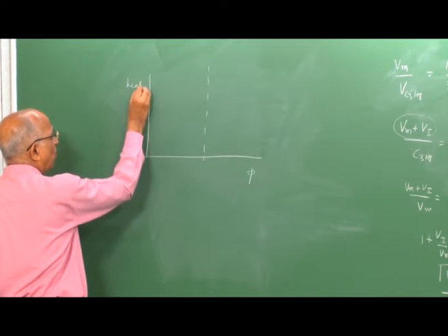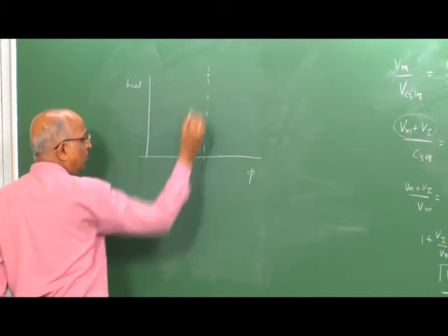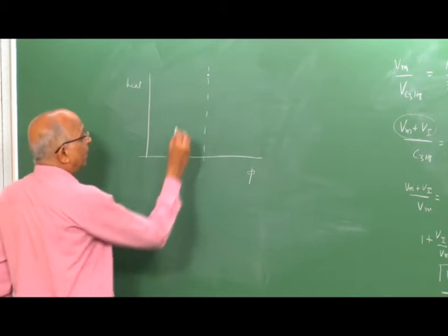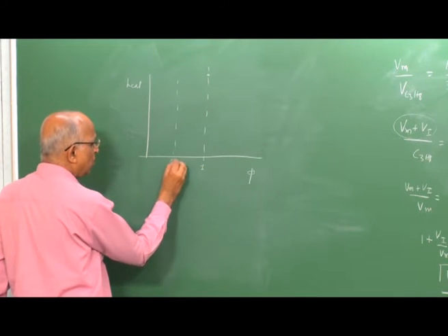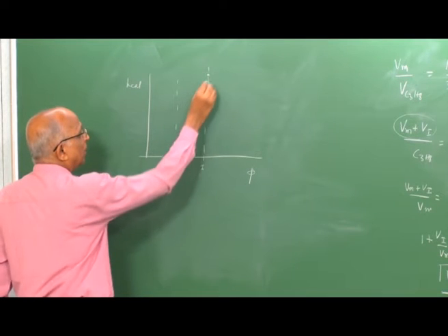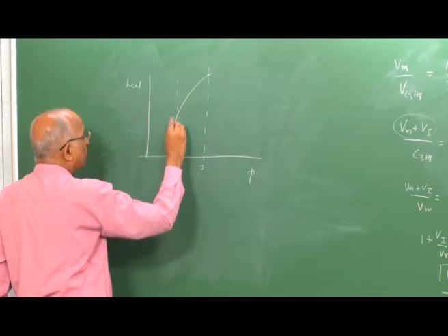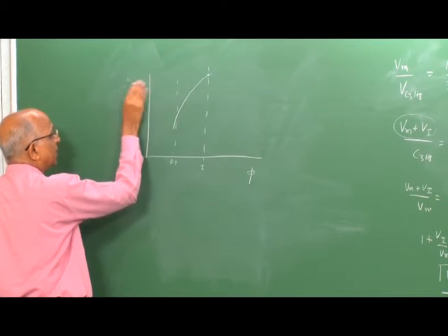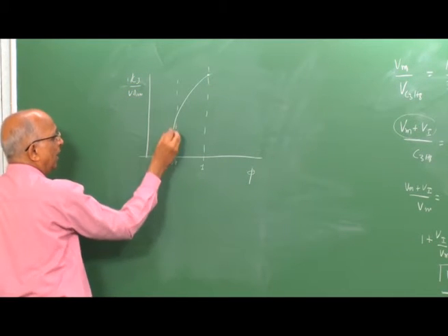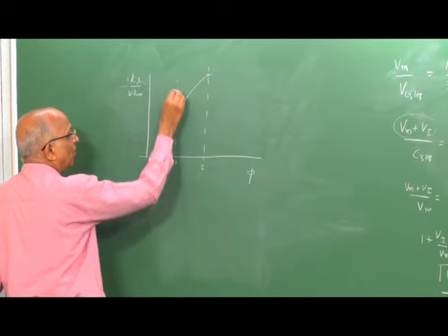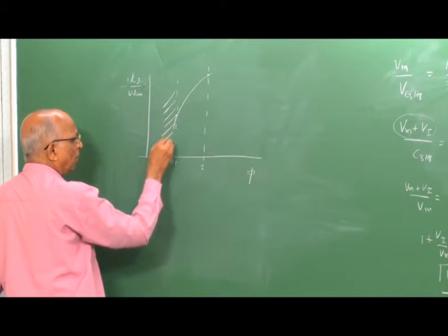The heat release is a maximum here, and when the equivalence ratio shifts from 1 to something like 0.5, nothing can burn. That means the temperature drops, because we are looking at heat release, say in kilojoules per volume or per mole of the mixture, and it drops to a value where it is not flammable anymore.